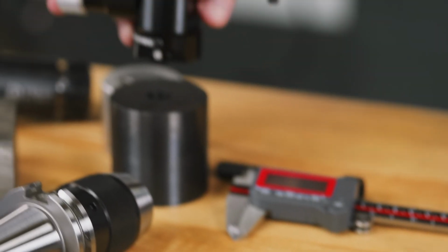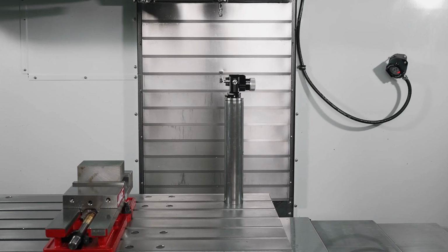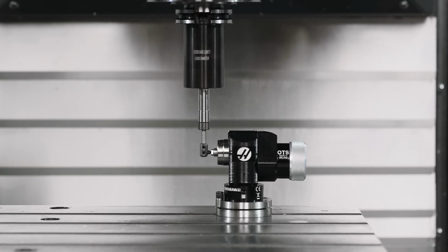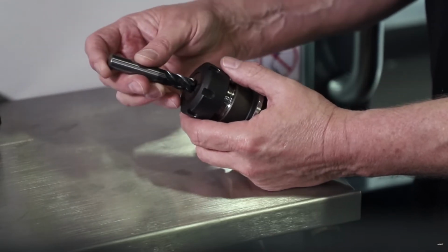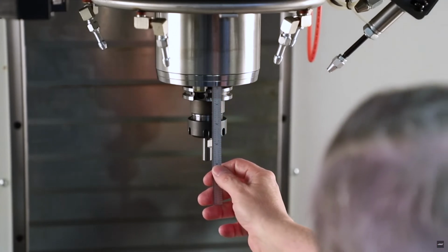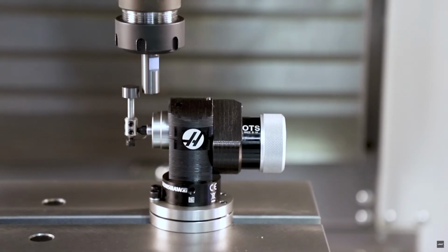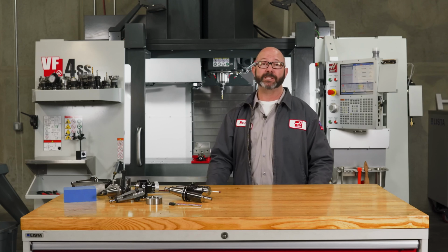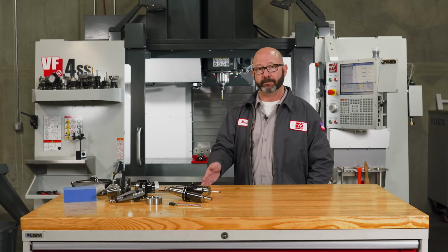Now the height of our OTS is not critical. We can use any spacer underneath it as long as we recalibrate to let the control know where the top of our OTS stylus is, compared to machine Z home. It is possible for us to create our own calibration tool by measuring from the spindle face to the tip of a pin in a holder, and using this estimated value when we calibrate. This is fine. Our probe won't be calibrated to some industry standard gauge line, but we can still probe and make parts on that machine.